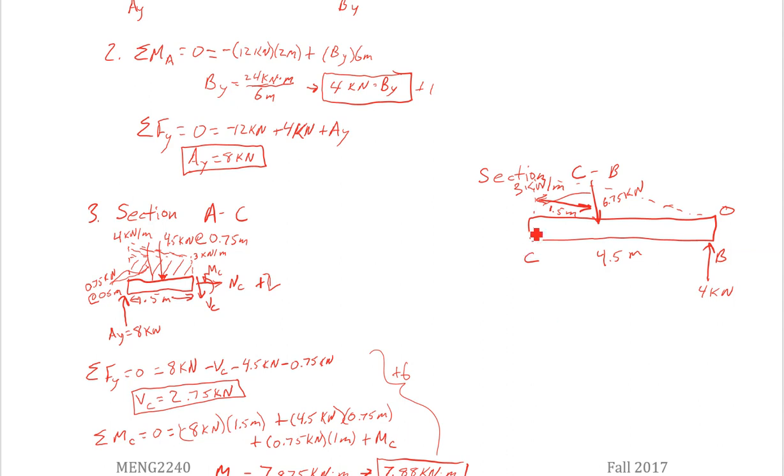And then I have my normal at C. I have my shear, it's going up, VC, and then my moment is clockwise, positive bending clockwise for that. Still a negative moment is my equations of equilibrium. So there's 2 points for that.